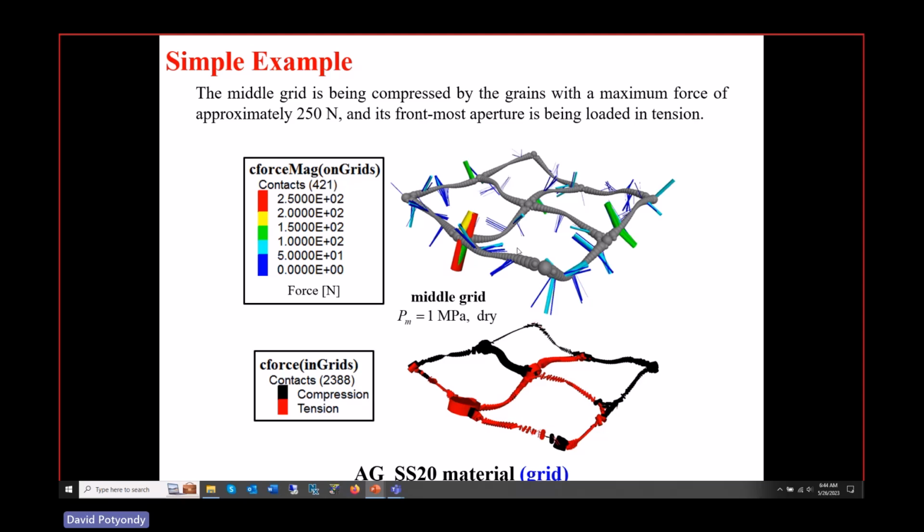And this is then just looking at the cement. And so in here, compression is black and tension is red. And so what you see is that this cell right here is under tension. This guy's getting stretched. It's pretty neat. So you're getting this interaction between the system and the grid then. And of course, since this has stiffness, it's getting pulled this way, right? That's holding the granular material in here, it's causing tension here. That means the granular material there is feeling compression, right? So it's holding it in there.